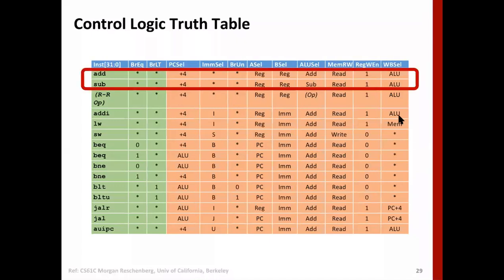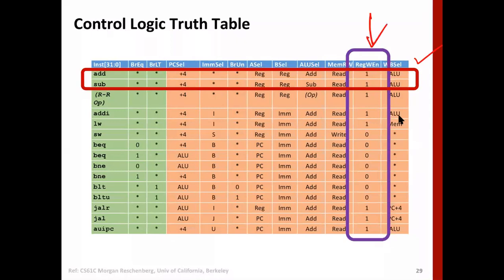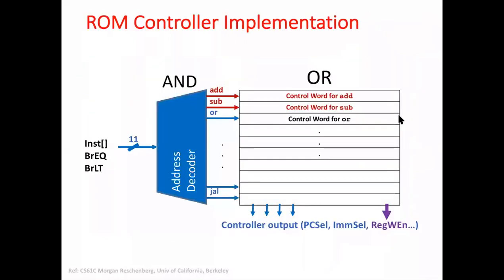So now we'll take this and try to code this corresponding to each instruction, right? So let's look at this bit, RW, the register write enable bit, and now create a circuit for this. So now we store the control word corresponding to add.